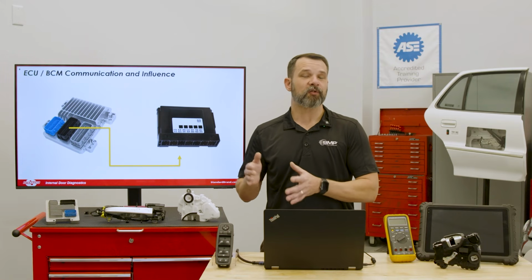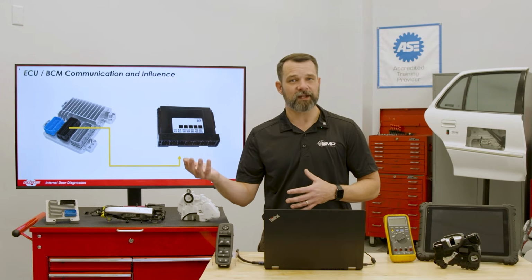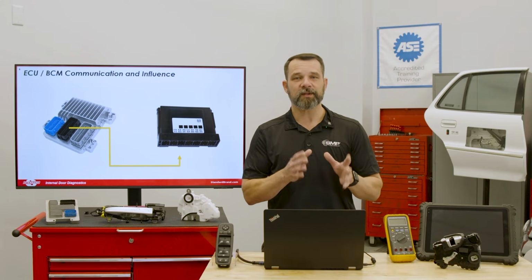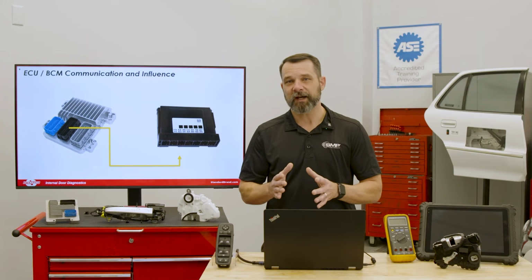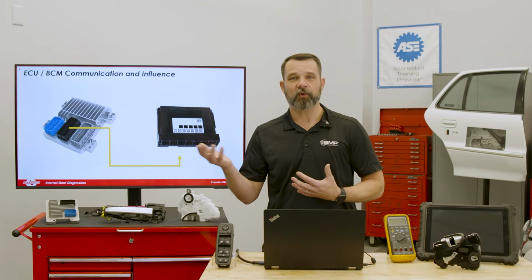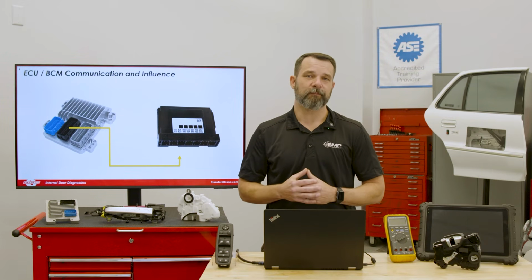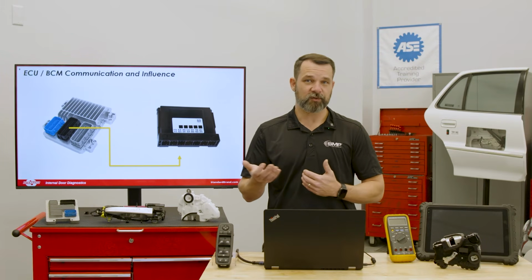It also looks at vehicle speed data for door locks, because auto locking is going to get triggered by vehicle speed data from the ECU. And the BCM is going to use that information to lock the doors at around that 10 to 15 mile an hour range. And that's why when we take off after starting the vehicle, usually rather quickly, the doors will all lock and sync.